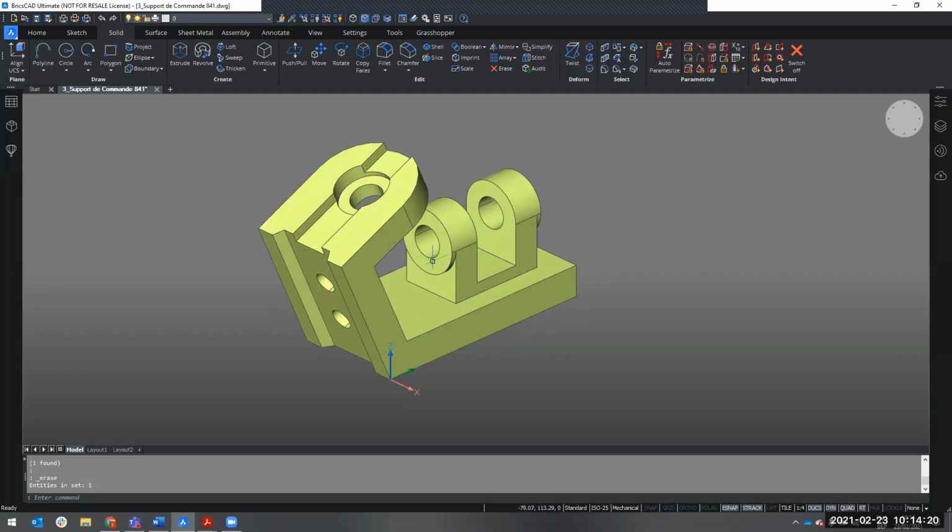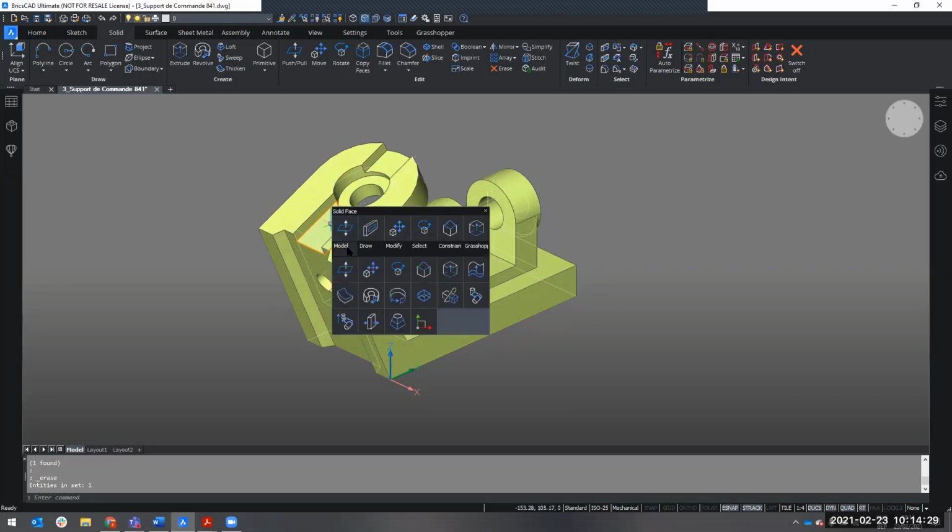Then we have the next step, step 5, that is deleting these, how do you call them, depressions. And that is also done in the Select tab, and this time with the depression tool. It's a box with a rectangle drawn on top of it. And you can select that one.